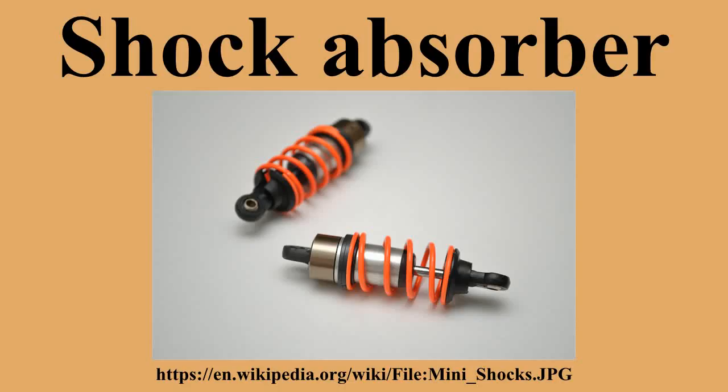Specialized shock absorbers for racing purposes may allow the front end of a dragster to rise with minimal resistance under acceleration, then strongly resist letting it settle, thereby maintaining a desirable rearward weight distribution for enhanced traction.